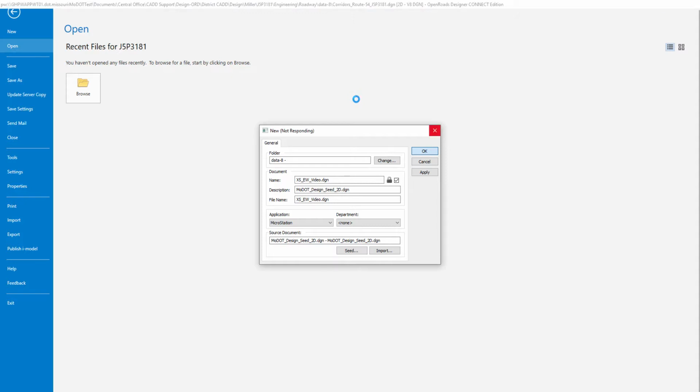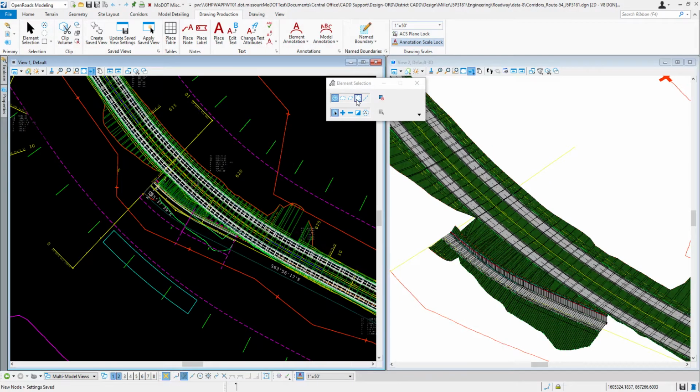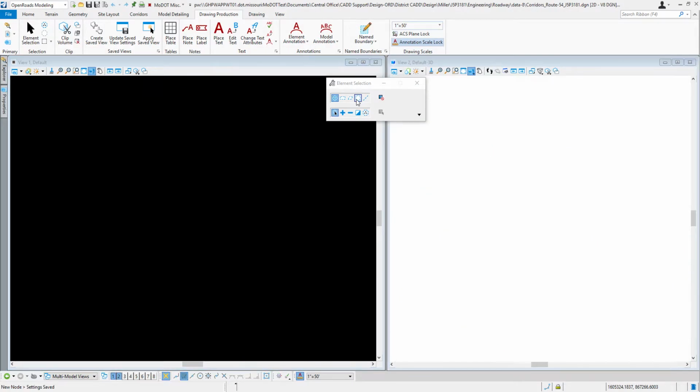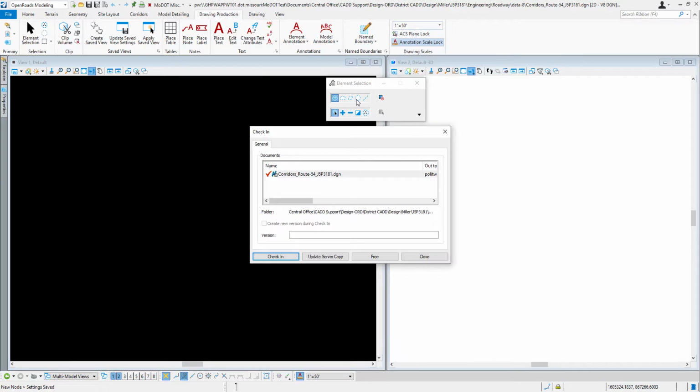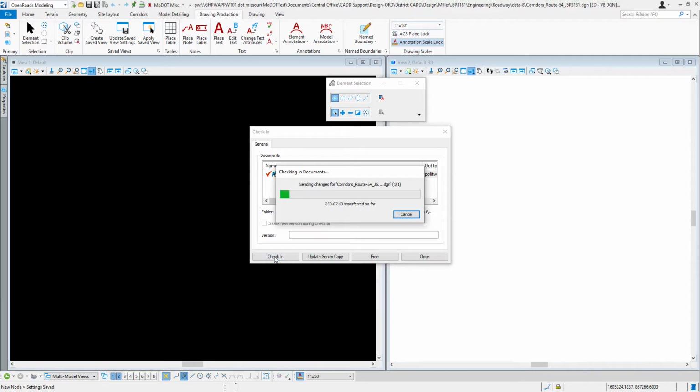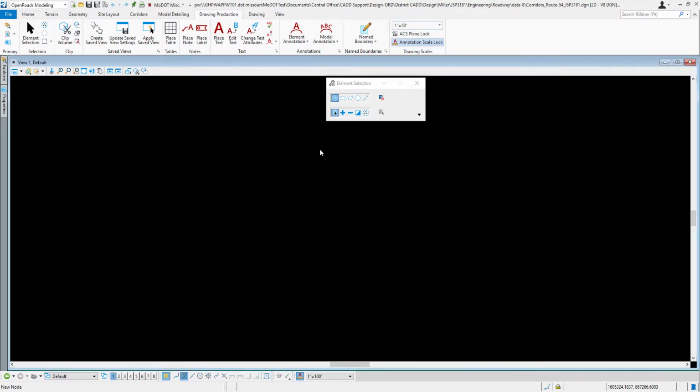And we'll take a moment for this to go out and create us a brand new file that's blank. Now, the way the process works is we're going to create some name boundaries out there, and then we're going to create a couple of meshes, one for the cut and one for the fill. And then we'll calculate from that, and then we'll go back and label our sheets with the values of the end area volume, or the earthwork. Okay, so here's our blank file.